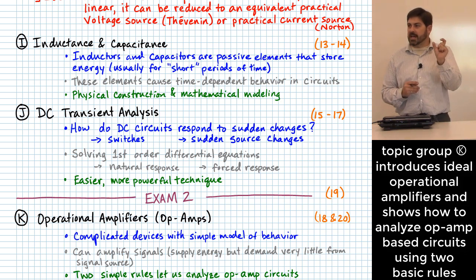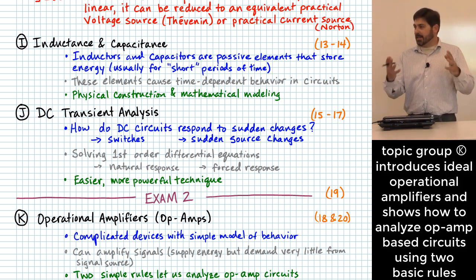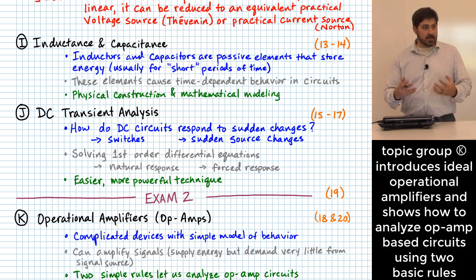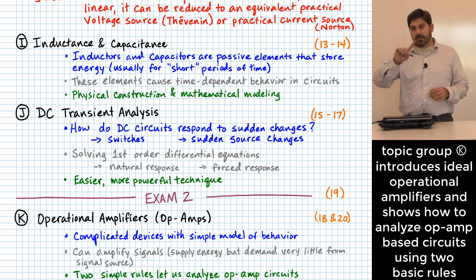Not to bring too much statics into our circuits class, but that's a device that can do that. But the signal that comes out of a strain gauge does not have a large amount of power capacity. In other words, it can't just automatically cause even a needle that sweeps on a gauge per se, because it doesn't produce power enough to do that kind of thing.